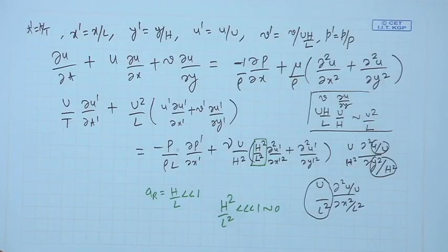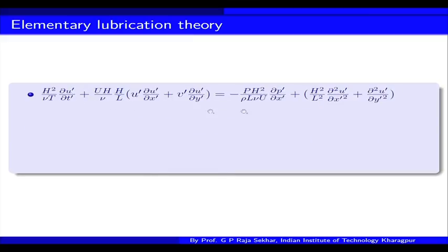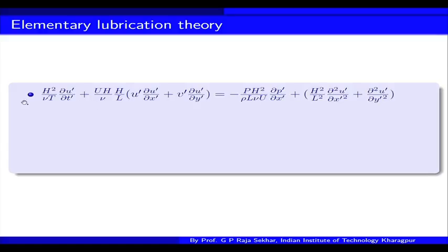axial variations. Okay. So, this is the non-dimensionalization we have done, and a similar non-dimensionalization is given exactly here, so this is a simplified version. Once we have this, the prefactor that we have is mu u by h square, so we have divided by that. Once we divide we get this. If you pay attention, this is nothing but the Reynolds number, and h by L is the aspect ratio.